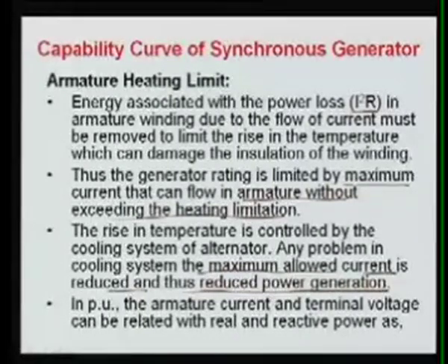Suppose your cooling system has failed or it is not properly cooled, then you cannot load your generator to its rated value. You have to operate your generator at a reduced rating if your cooling system is not perfect.